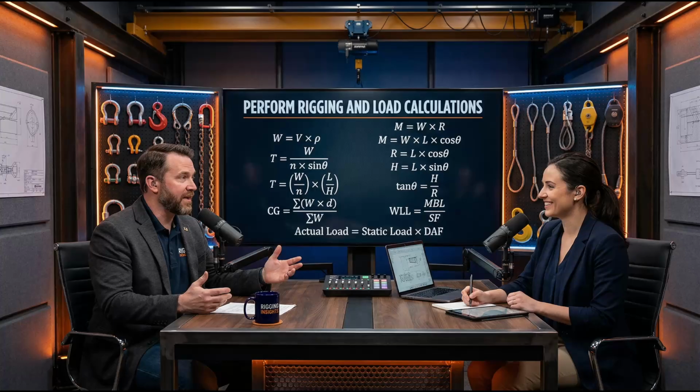Simple on paper, yeah. Exactly. But it looks simple, and then it is incredibly unforgiving in practice. The foundational rule across all our sources is that guessing the weight of a load is never acceptable. Ever. You can't just eyeball it. No, you cannot just look at a piece of machinery and estimate. You have to calculate the physical space it occupies first, its volume.